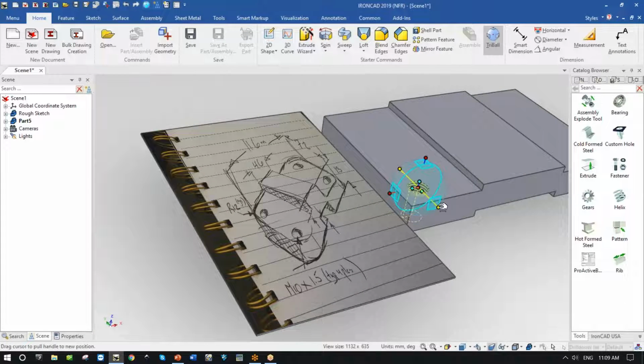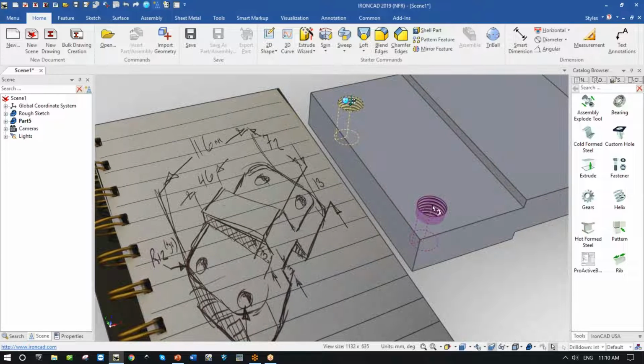Now watch this. I want to move this over to the other side because I need 4 of these. They're typical. All right, easy. Grab this center hole and move it all the way to the other side. There, snap to this line. Great. Link this there. You know what? Not on the edge. Move it back 10 mil. Super easy. Now I've got that one over on this side.